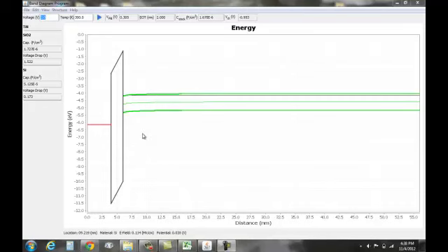Let's say I want to go into a specific material and know the electric field at this position. I can see in the bottommost panel that it says 7.6 megavolts per centimeter. Now let's say I wanted to copy that electric field so that I can use that number for calculations outside the program.